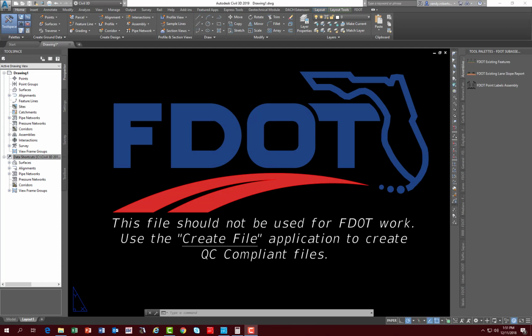Concerning FDOT standards, FDOT provides several resources to instruct and aid designers in computing pay item quantities. The Estimates Office publishes the Basis of Estimates Manual, the governing document that specifies how to compute each pay item. The Estimates Office also provides a master pay item list containing every pay item available for use in Florida. The FDOT Civil 3D State Kit provides tools to simplify the process of generating quantities.